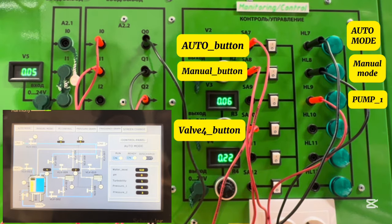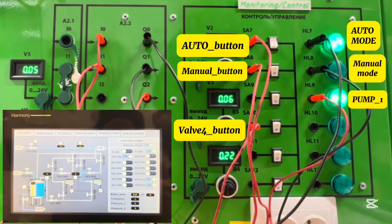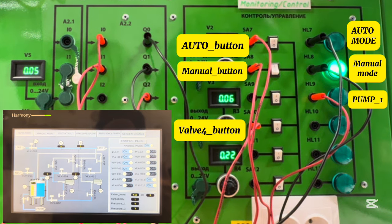We start on the auto mode screen of the HMI. On the stand, we press the auto button, the auto mode activates, and pump 1 turns on automatically. Next, on the HMI, we select manual mode and the screen changes. Then on the stand, we press the manual button and the manual mode indicator lights up.